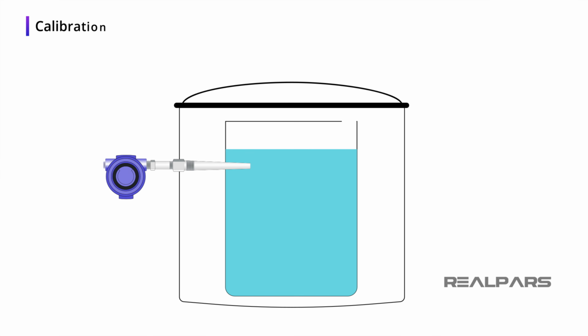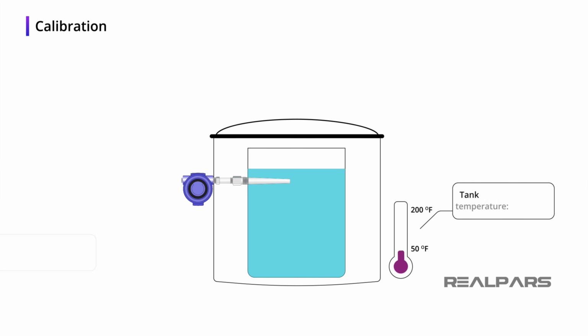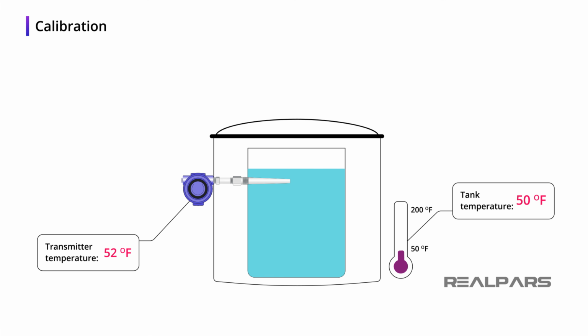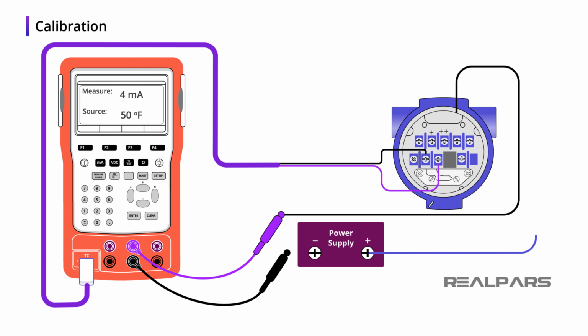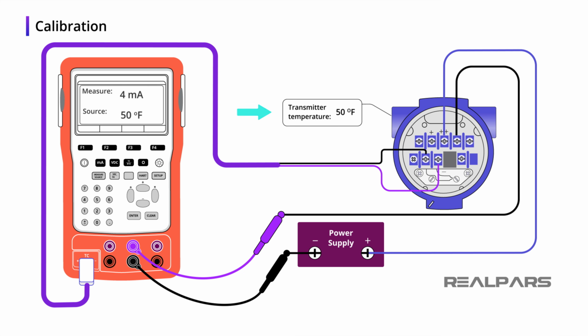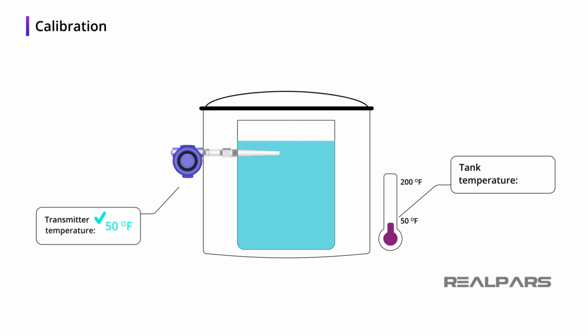Okay, so what is calibration, and what is an instrument calibrator? If the quantity being measured is not being accurately represented by the measuring instrument, it possibly requires calibration. We can replace the quantity being measured with an instrument calibrator. Calibration can be carried out by comparing the readings on an instrument with those given by the instrument calibrator. Instrument calibration is an adjustment or a series of adjustments performed on an instrument to ensure that the instrument readings accurately represent the quantity being measured.